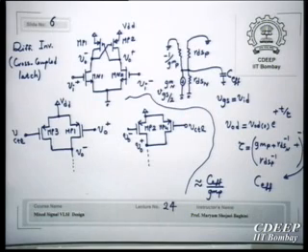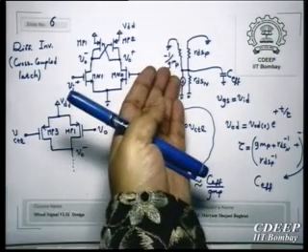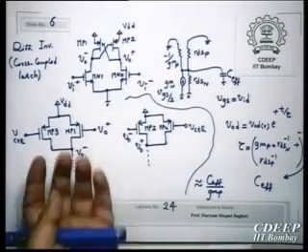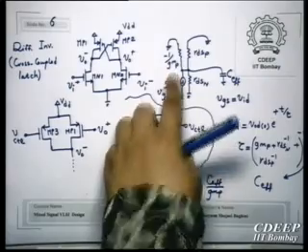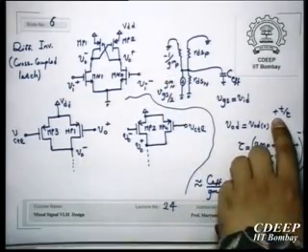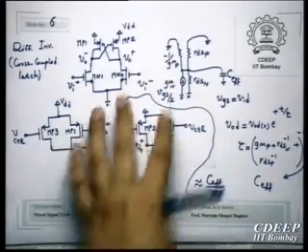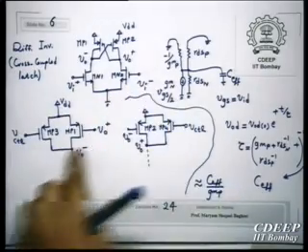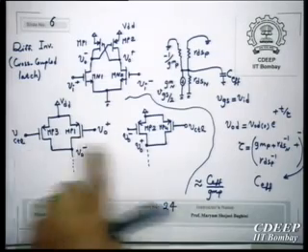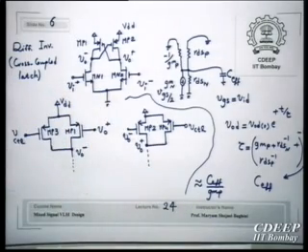Now, when I add this, what we are doing is adding two resistors in parallel to this negative resistor. Now, if I make it more than this, effectively I'm creating a negative feedback system. However, now I can control the delay, because still it will be a differential amplifier, but still it can have a rail-to-rail swing.